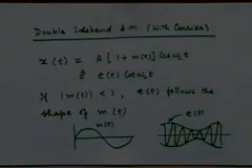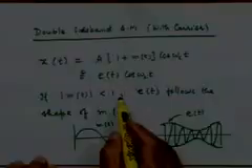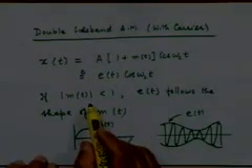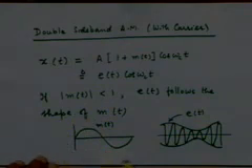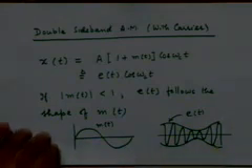If it crosses the time axis, we will have a problem, because then we will lose the proportionality of the envelope that we are looking for with respect to m(t). So that's why this condition is required, that the mod of m(t) should be less than 1, right? So that's the typical time domain waveform of amplitude modulation with carrier, as against the waveform that we saw yesterday for amplitude modulation with suppressed carrier, without carrier.